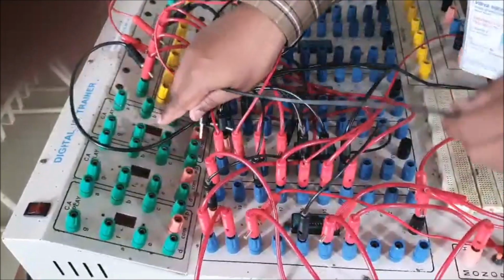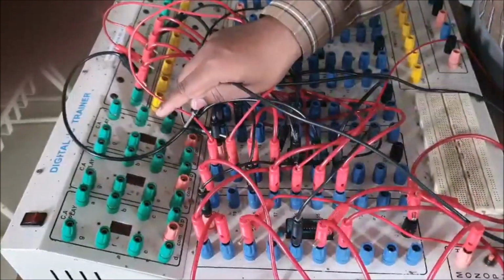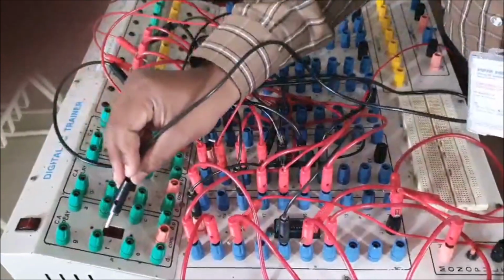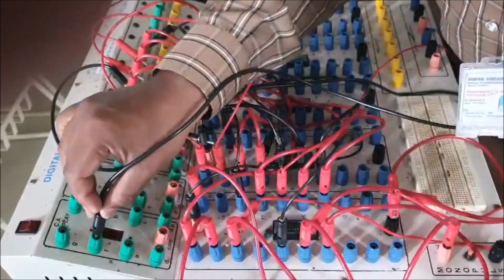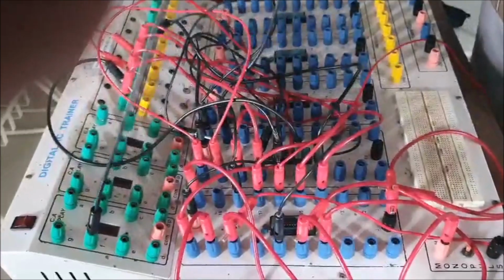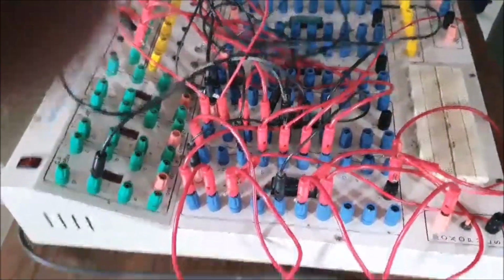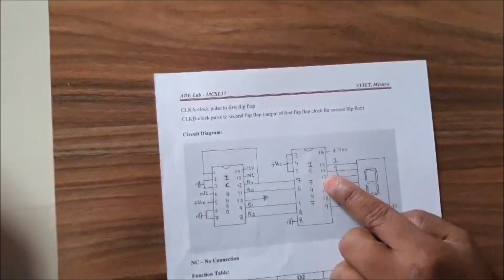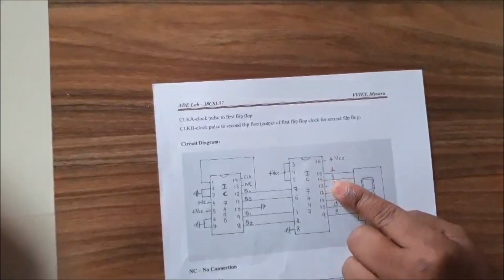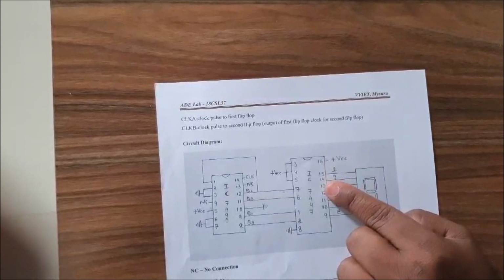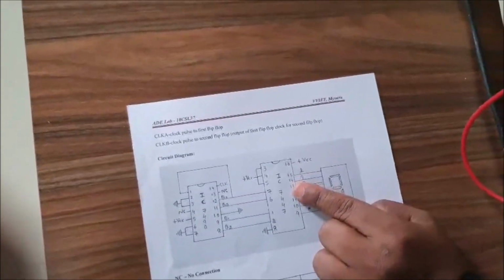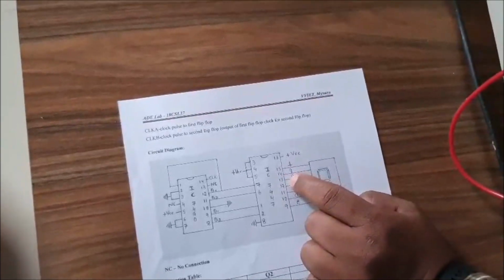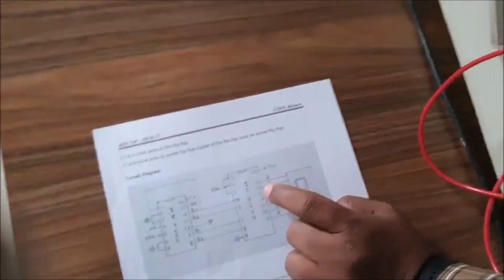This is the 7 segment display. There are 3 7 segment displays here. I will take up the first 7 segment display. Another end of the patch cord is connected to F. This is the F pin of 7 segment display. Next, I will take another patch cord. So now I need to connect for G. G belongs to the 14th pin of 7447. One end of the patch cord should be connected to 14th pin. Another end is connected to the G pin of 7 segment display.